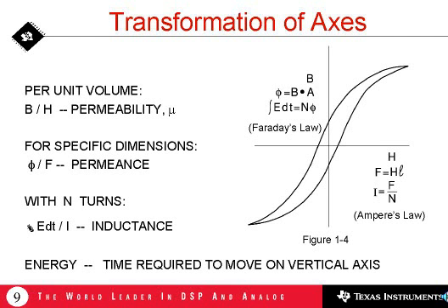If we multiply the flux density axis of this drawing by the magnetic cross-section area of the specific core we are planning to use, the flux density axis becomes transformed to total flux. This assumes that the flux density is uniformly distributed in the cross-sectional magnetic area of this core. This assumption is good enough to result in acceptable accuracy.